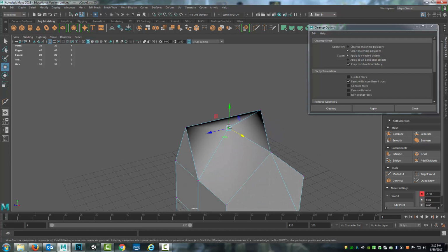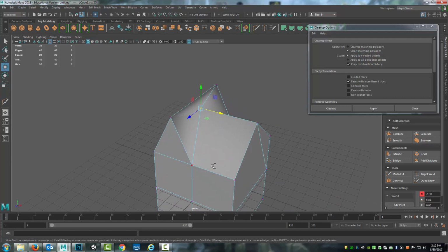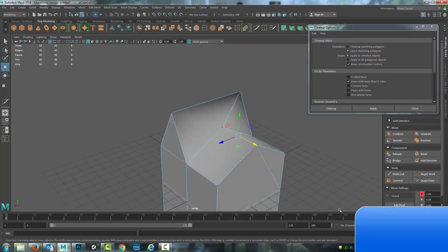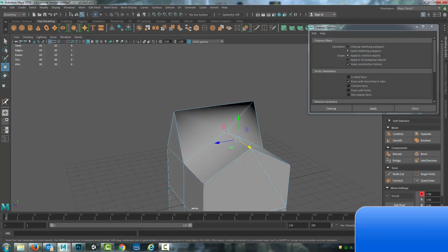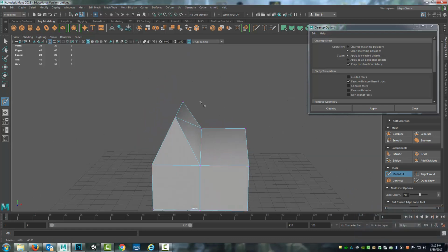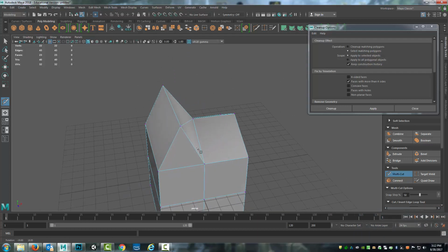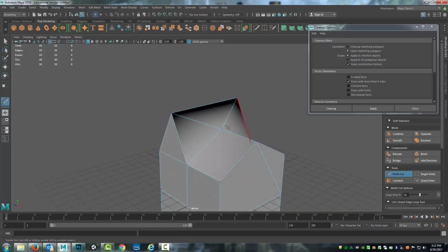And so you want your quads not to have concavity on the edges. So I'm going to take that back a little bit. And you can also add this in, and yay, now I've got 3 triangles across the top so that we don't have the same issue we had a second ago where it was folding over, but it's actually got these edges. But this isn't really the most efficient way to do it.